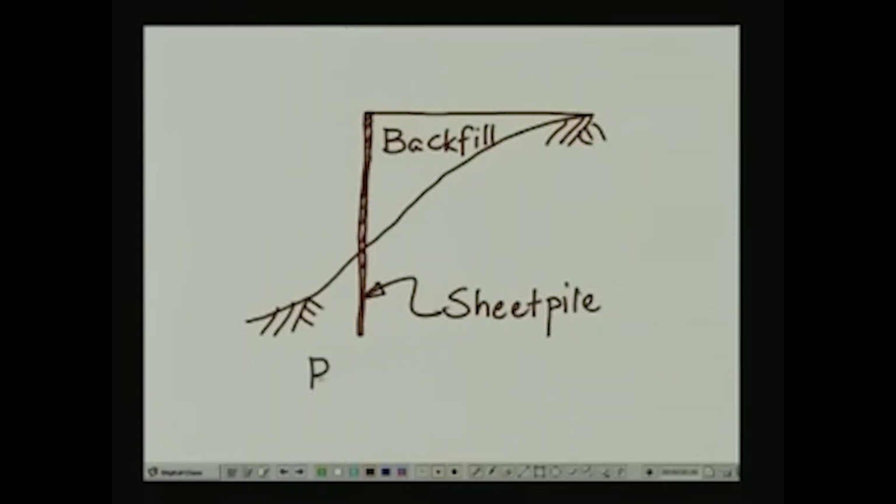So this one here is called a bulkhead. This is not visibly very appealing, because at the shoreline you are going to see the face of the sheet pile wall or any such wall that you might actually construct along the waterfront. So in this case, the water is going to be like this, and the coastline is going to be reshaped like that.